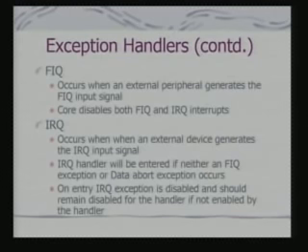On entry, IRQ exception is disabled and should remain disabled for the handler unless enabled by the handler. That means, if I am not entertaining nested interrupt processing, I shall not do what? Enable IRQ inside the IRQ handler. If I am not enabling nested interrupt handling, there may be increased interrupt latency.